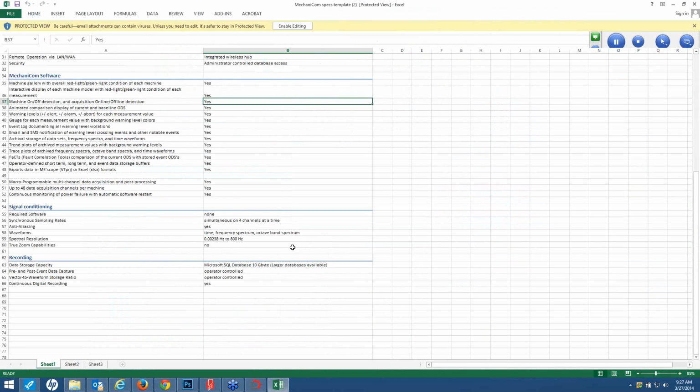So, have you got strain gauge amplifiers, like Vishay or something like that? Some kind of strain gauge amplifier that you could put a strain gauge on a bridge, if that's a setup that you want to go through, then yeah, I mean that's what we put in as part of the front end. Part of the acquisition, we just change out what we have in there if you're primarily going to run the strain. But yeah, that is certainly available.